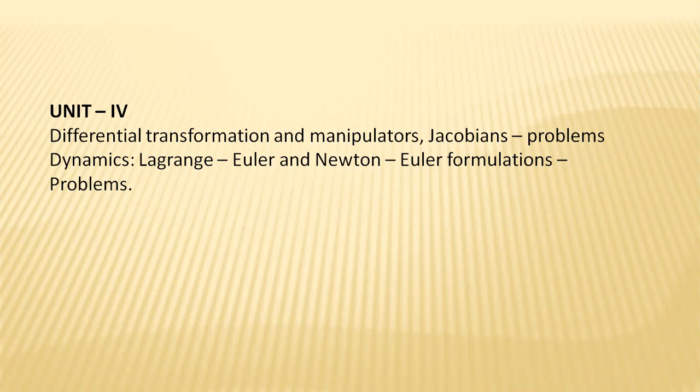As per our trigonometrical values considered in the forward kinematics, based on the coordinate frames, we have solved the problems. For example, in coordinate one, the robot manipulator or link 1 is rotated with respect to theta 1, and it is rotated with respect to theta 2 by the link 2 and translated by 8 units along the x-axis. So this is the minimal kind of problem that we have already solved in the case of kinematics of machinery.